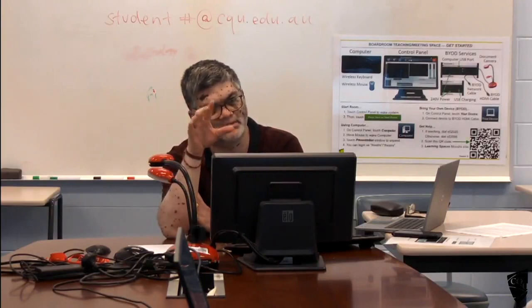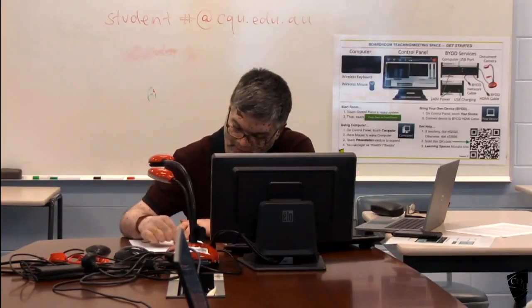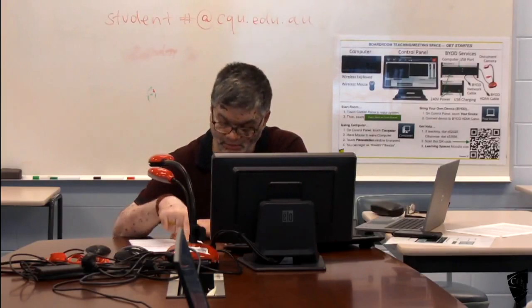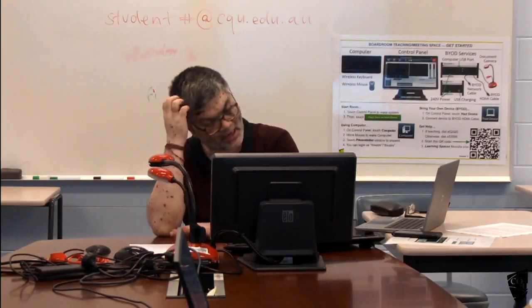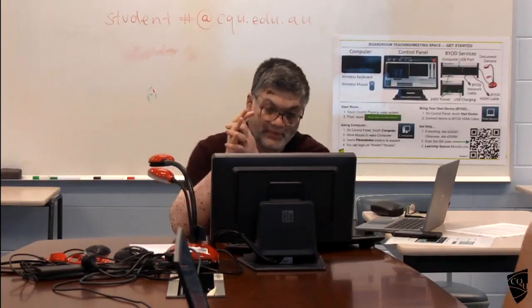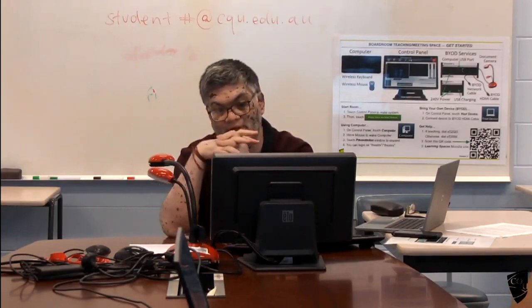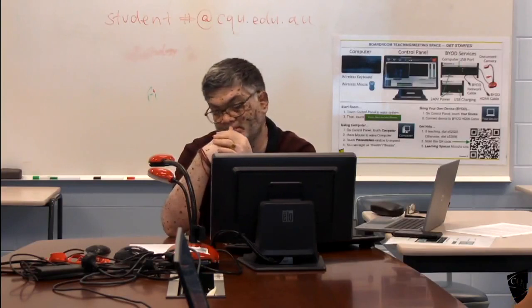Here it's not 1 meter, because it differs at each location. If you take 1 meter from here or here or here, it is different. So we can't use a 1 meter strip. So we use the design strip. It will be more than 1 meter.